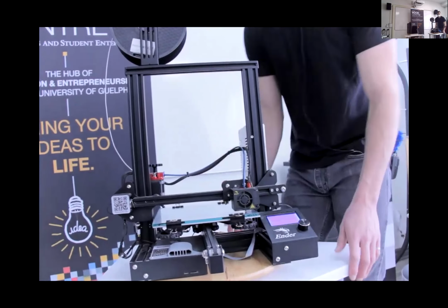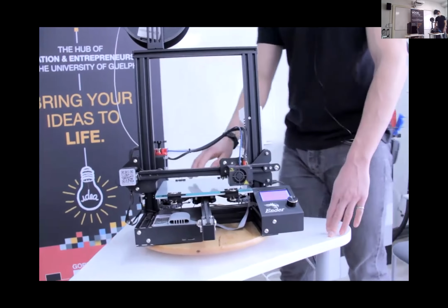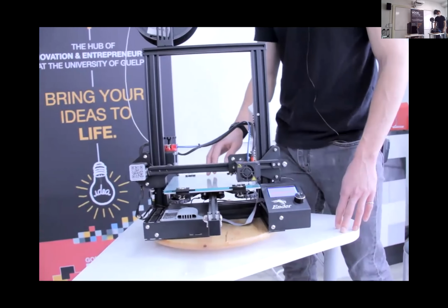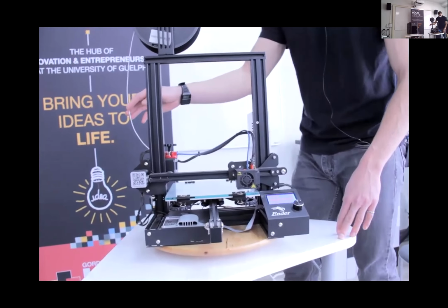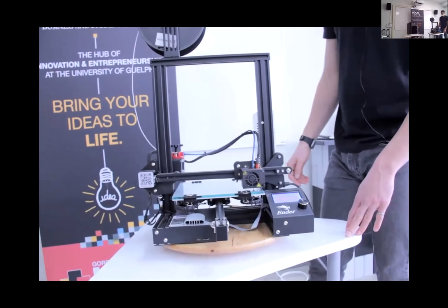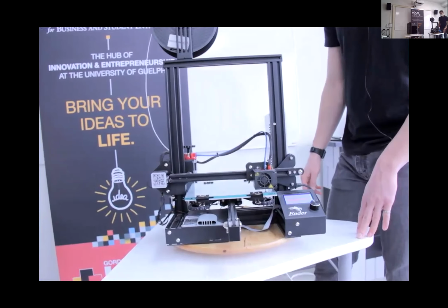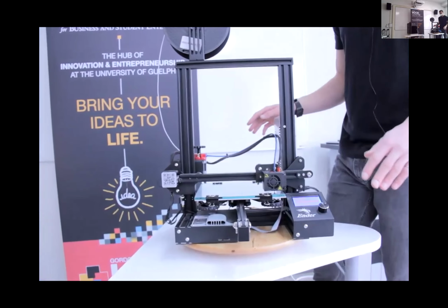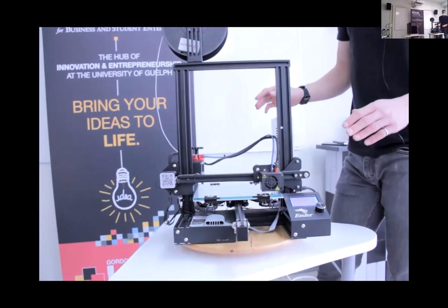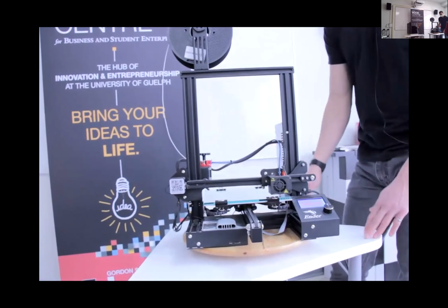The first thing I want to check with the printer is that the bed is nice and level. So this is the print bed here. This is where our prints get printed onto. And if it's not level, our melted filament's not going to stick, and we're going to have to stop our print because it's just not going to work. So we better check that our print bed is level. If you've done a print recently, you don't need to do this every time. But let's pretend we haven't done this in a while. So we're going to check that our print bed's level.